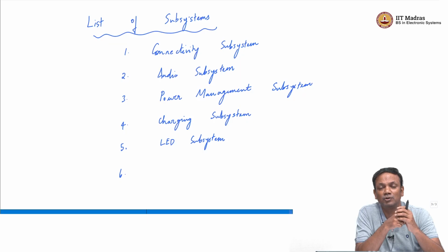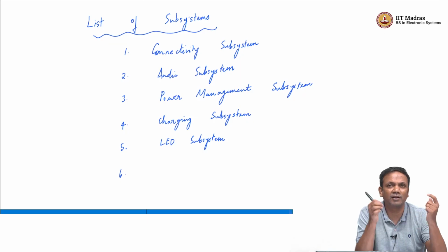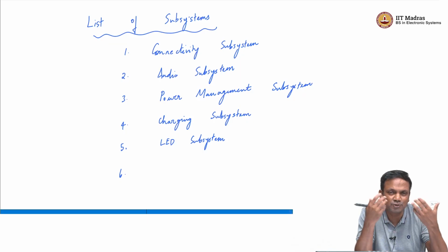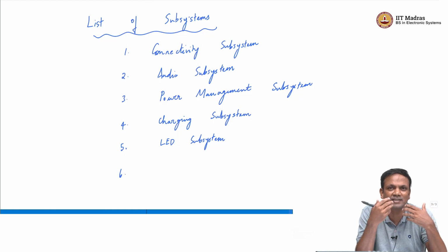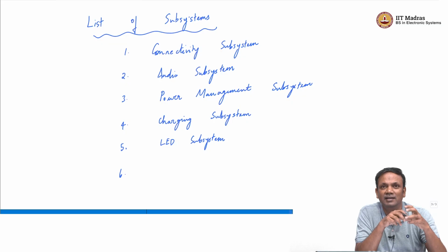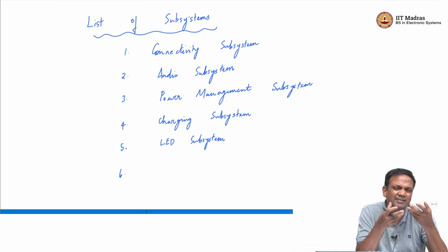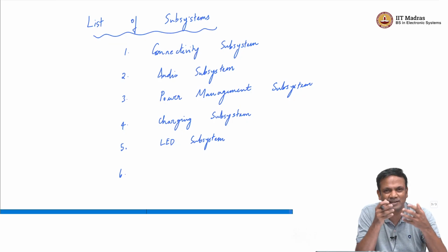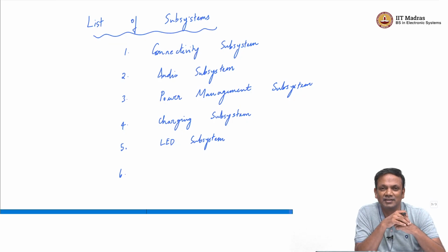That it is able to say, oh, now you've plugged in, I should detect that, I should play a tone, show something that tells you that I understand that you plugged in the earbud. That is achieved in some cases through an IR sensor. You can have a range of different ways in which you can detect it. Sometimes they have a combination of a pressure sensor and an IR sensor.